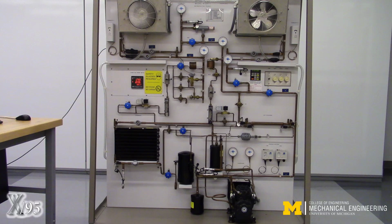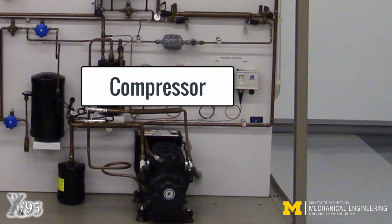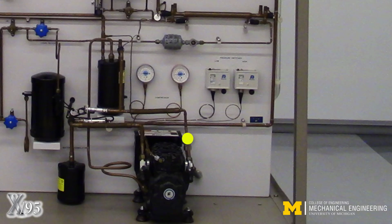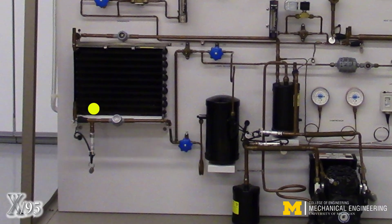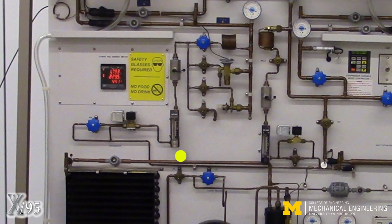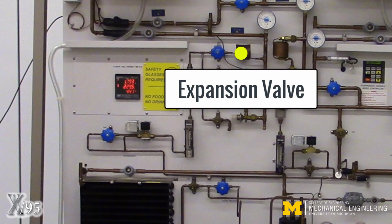We recommend physically tracing out the circuit. Start at the compressor outlet and follow the freon path by tracing the copper tubing over to the condenser. After passing through the condenser, the freon will loop around and will eventually pass through the 2 flow meters before moving on to the expansion valve.